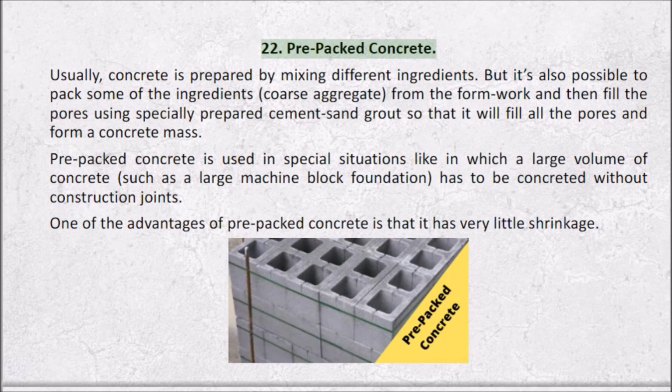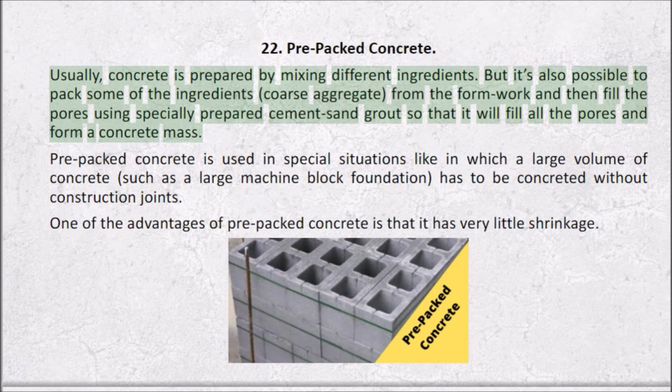22. Pre-packed concrete. Usually, concrete is prepared by mixing different ingredients. But it's also possible to pack some of the ingredients, the coarse aggregate, in the formwork and then fill the pores using specially prepared cement sand grout so that it fills all the pores and forms a concrete mass.